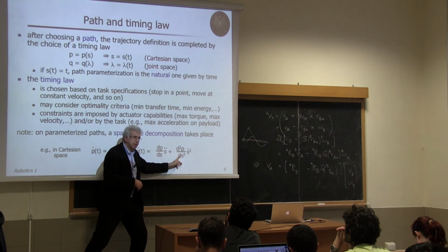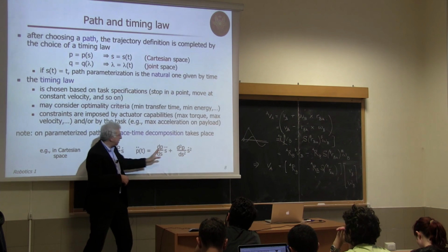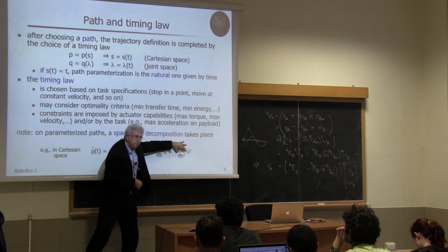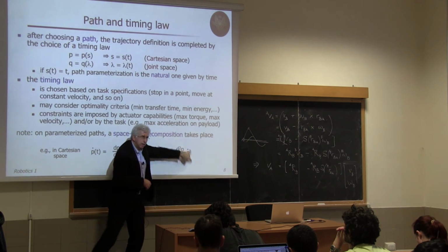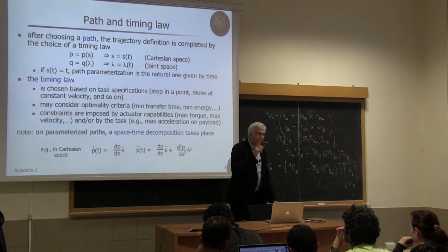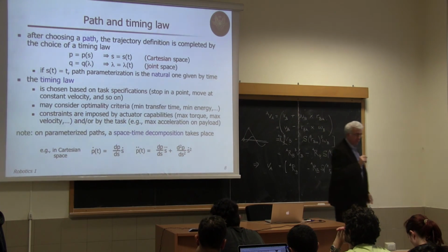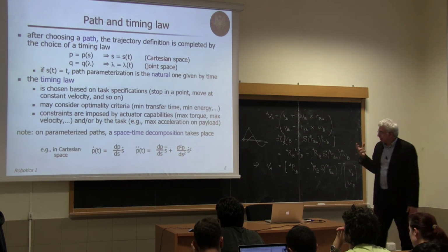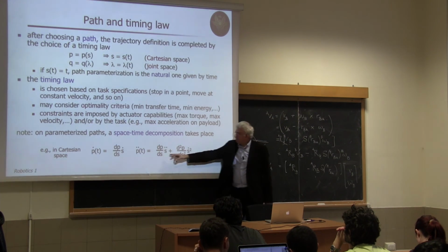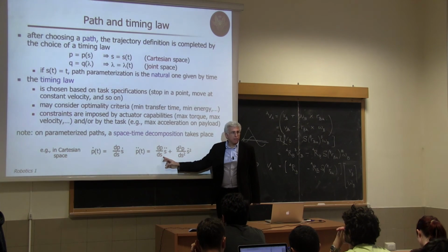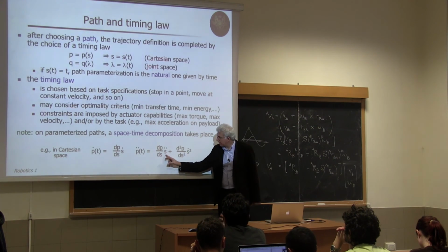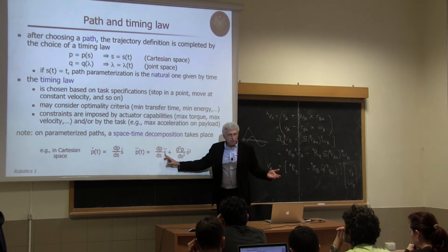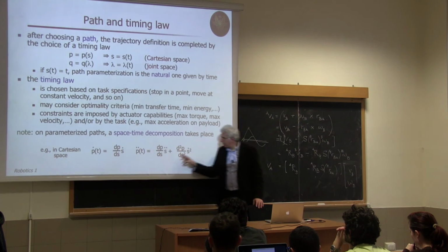So this is something else. In fact, in this acceleration, I can decompose in this way the tangential acceleration and the centrifugal acceleration. Okay? Especially if s is the arc length parameter. Otherwise, this is not true. There is some more complex formula for obtaining it. But you can immediately see that if I'm moving at constant speed, which means that s double dot is 0, s dot is constant, I may still have different acceleration if this changes.